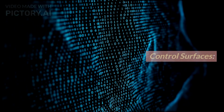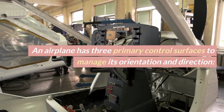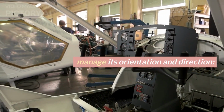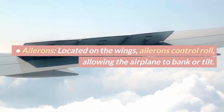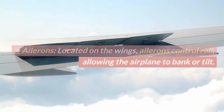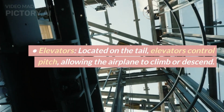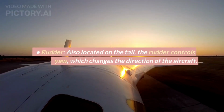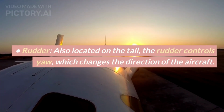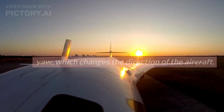Control surfaces. An airplane has three primary control surfaces to manage its orientation and direction. Ailerons, located on the wings. Ailerons control roll, allowing the airplane to bank or tilt. Elevators, located on the tail. Elevators control pitch, allowing the airplane to climb or descend. Rudder, also located on the tail. The rudder controls yaw, which changes the direction of the aircraft.